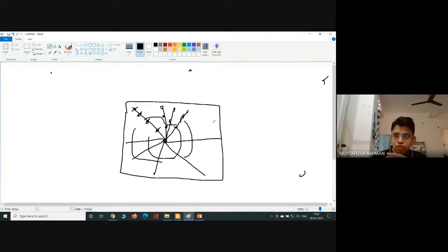Now, in doing all these things, one thing is very important. I have already told you, you may know this already, but still I would like to say once more: always mark the north direction corresponding to our work. Because with the help of direction, we will find out everything corresponding to this location, this place. Whatever survey work we do, we always need the direction, to know which way we are going, which way we are doing the survey. If it is a building plan, then also we need the north direction, because corresponding to the direction, we shall plan our rooms and different things.